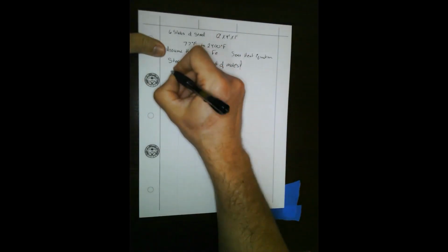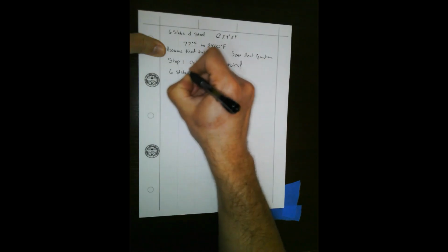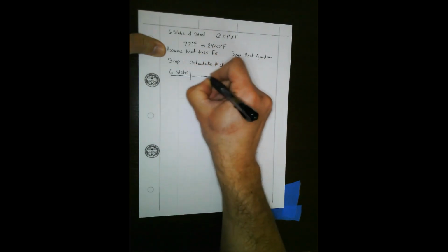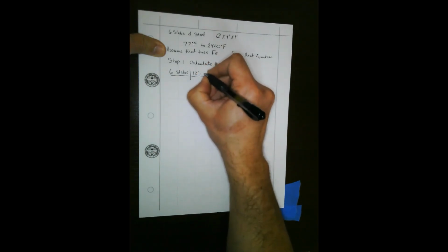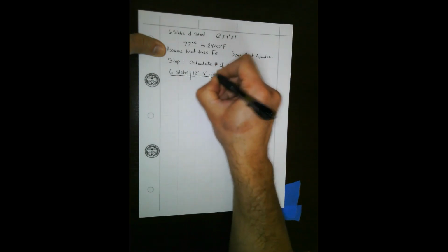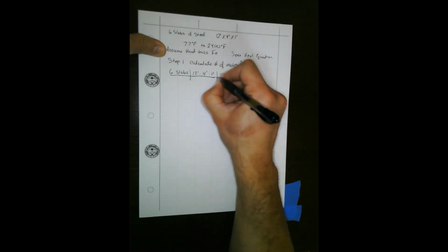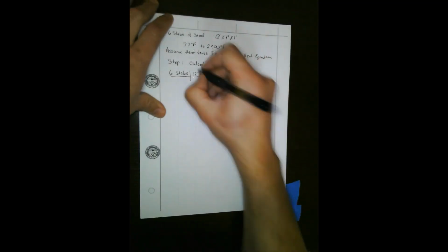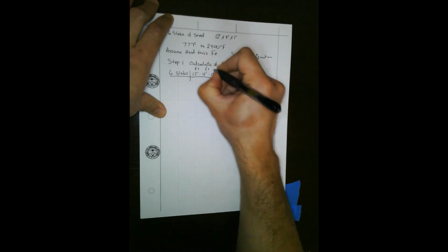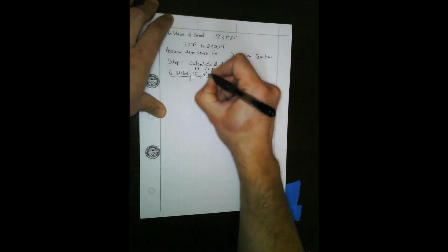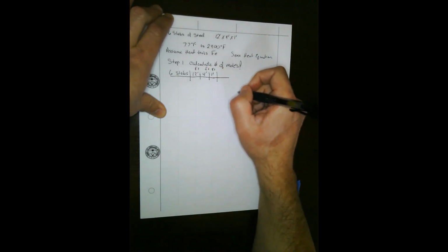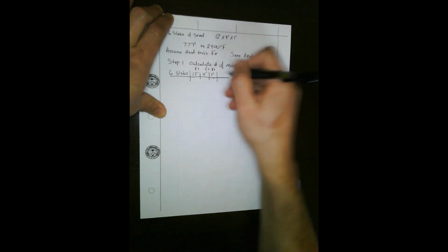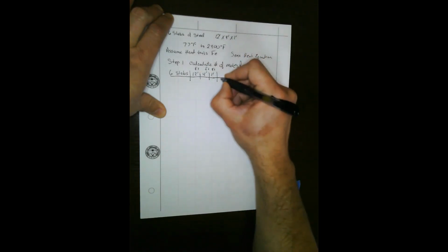And so we have 6 as our basis, and it's 12 foot times 4 foot times 1 foot, and that's a cubic foot, and that probably should be a little bit better in terms of units. So we have 12 times 4 times 1, those are all feet. We have cubic foot per slab, so we can cancel slabs.